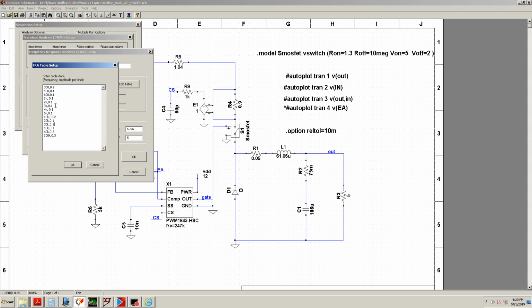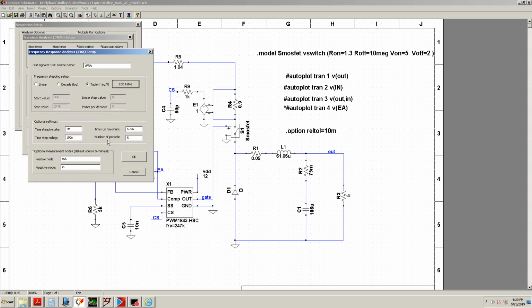As the frequency is stepped up, the amplitude goes down, and in this, there seems to be a resonant frequency at 10K. I want to decrease the amplitude and then increase it back up. And if you notice, on the last 60K and 100K, I need much more signal because the attenuation at those frequencies is very low. So in this case, I have a very powerful FRA, because now I can specifically set my signal amplitude.